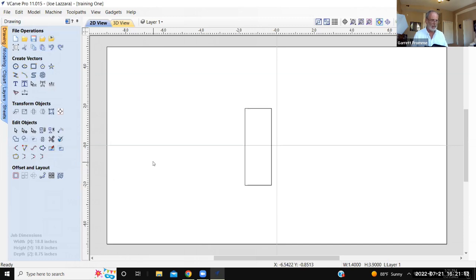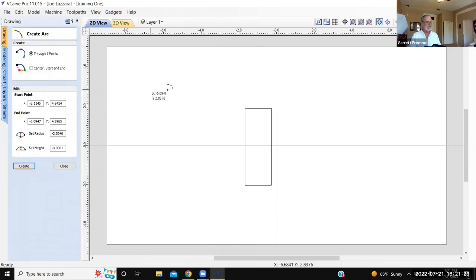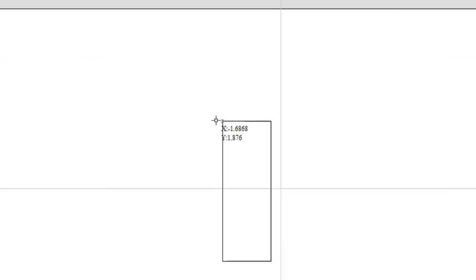For an arc, let's say I want the top of this, I'm making a silo. So I need a roof on there. The arc is perfect. I select the arc, I come down and let it snap to the corner there. You see how my cursor is changing? I'll snap it to that corner there and I just draw it up. Hit escape and there's the silo.